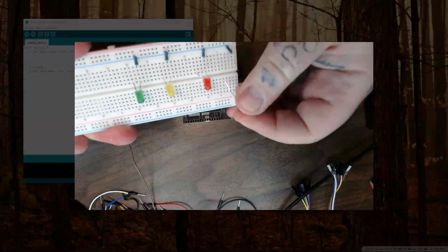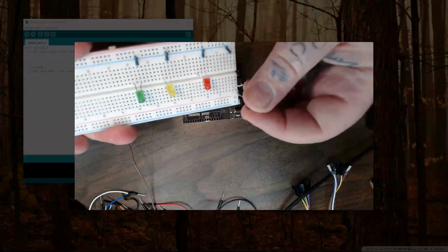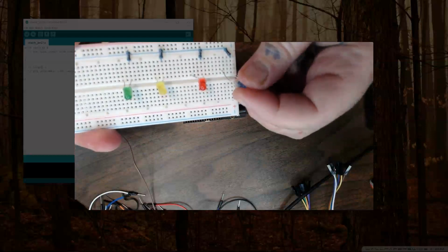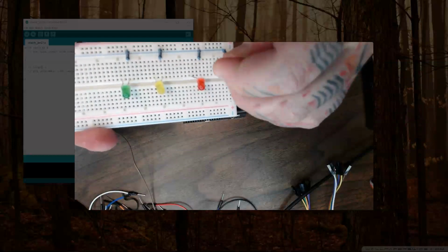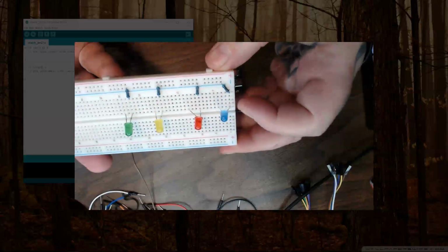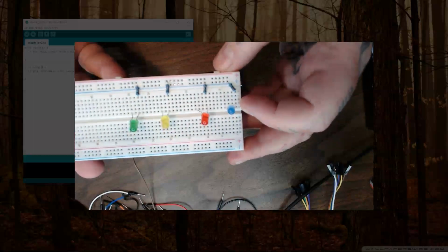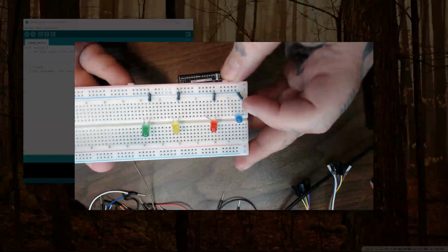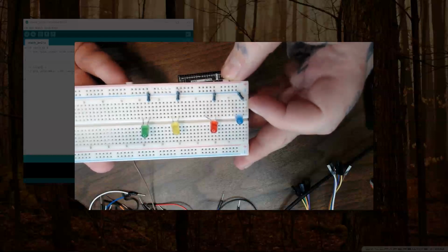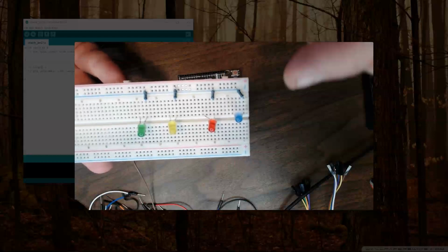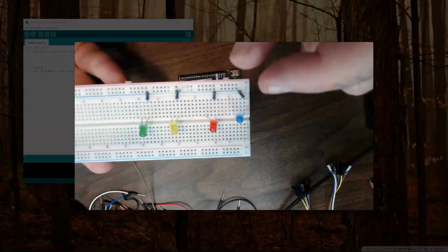You can pull it out and see from right here, the longer end and shorter end. It's the anode here and the other side is the cathode, so the short side I'm putting into the board. I have cut the leads on all my resistors to be shorter. I would not suggest doing this yourself. I know I don't need them again, and I just didn't want huge wires sticking up, so I cut the metal on each side a little bit shorter and shoved them in. I kept a little bit longer part of the lead, just made them shorter.